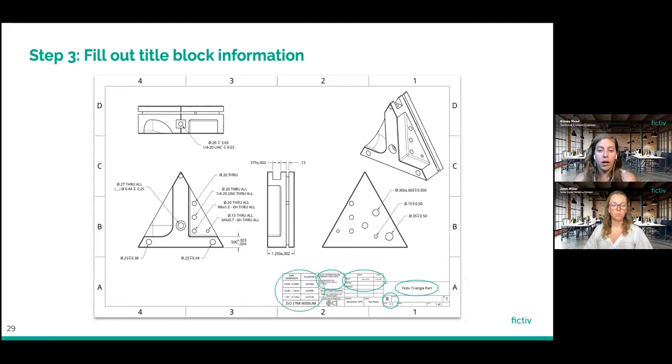Then we have notes on tolerances. So in this case, the tolerance depends on the size of the feature according to ISO 2768 medium, which is our standard that we're using here. Sometimes you will see that the tolerance depends on the number of decimal points in the dimension. So again, super important to pay attention to as you're dimensioning the drawing and if you're interpreting the drawing.